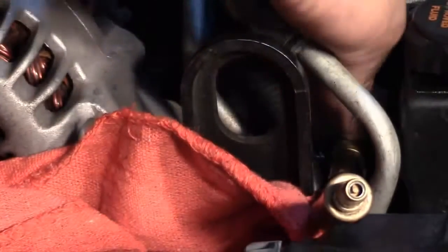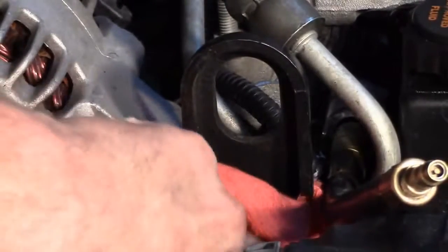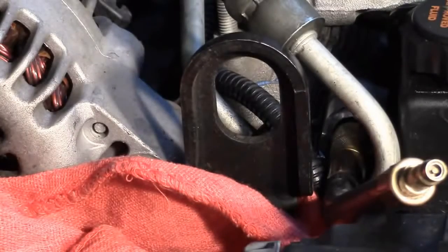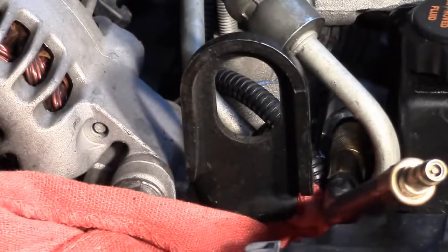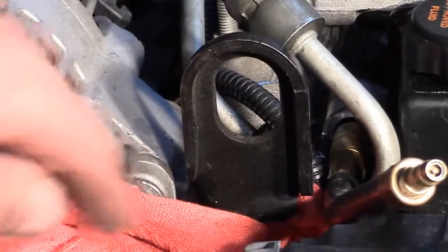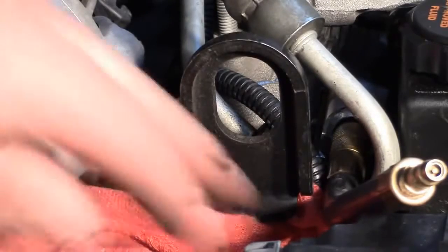So the first thing I'm going to do is hook up my fuel pressure gauge hose to the Schrader valve. This vehicle luckily does have a Schrader valve. I hate those demonic, sadistic engineers that do not put Schrader valves on cars. Why do they do that? You might as well put the diagnostic link for the scan tool inside the gas tank as far as I'm concerned. Notice I've got a shop rag here so I catch any spilt fuel.